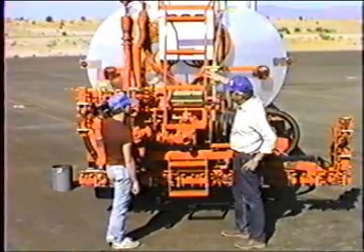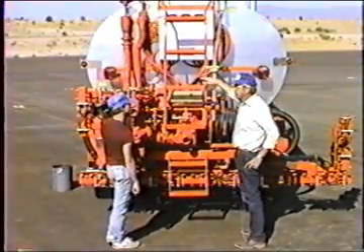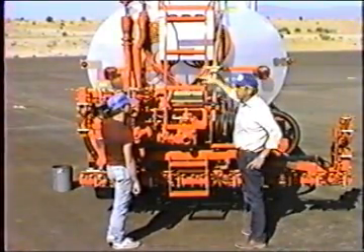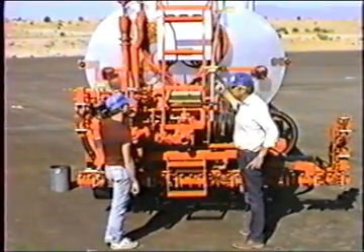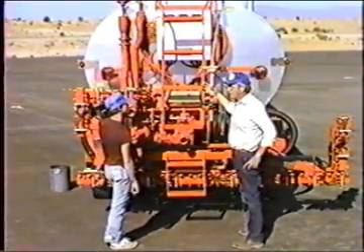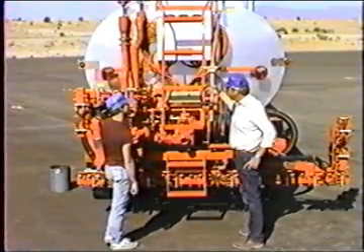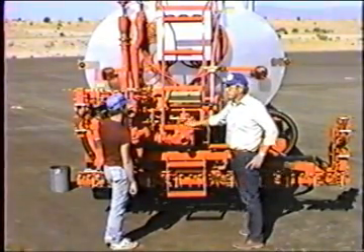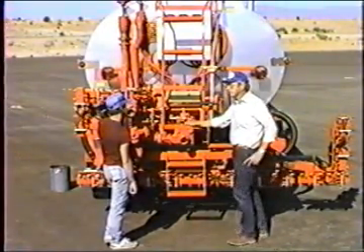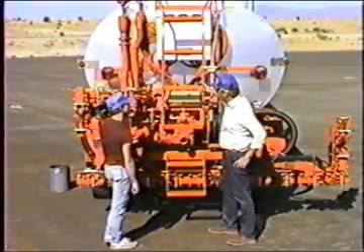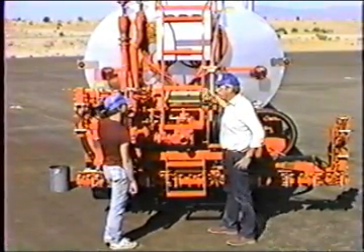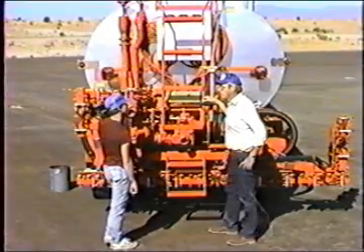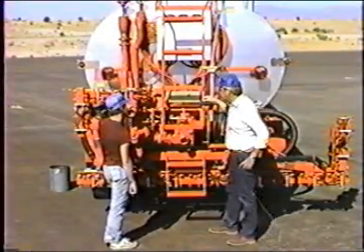If you heat a lot in this tank, if you heat every load and you don't circulate the way I'm telling you to, within a month's time it'll start to coke up bad, and that coking breaks off. Then from then on, you're going to clean this screen for every load. It's a guaranteed deal. If you're very faithful about circulating and never heating without circulating, and you do get good supply, then you'll have minimal screen cleaning.